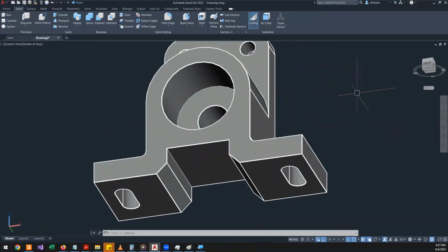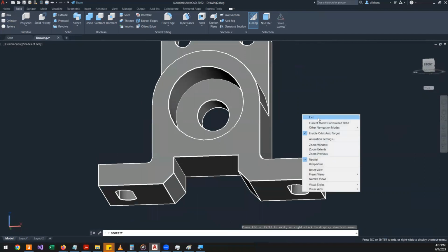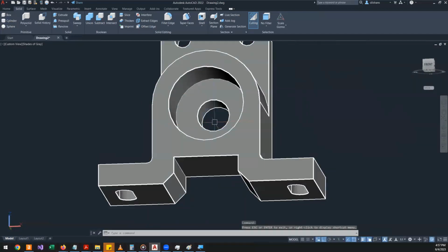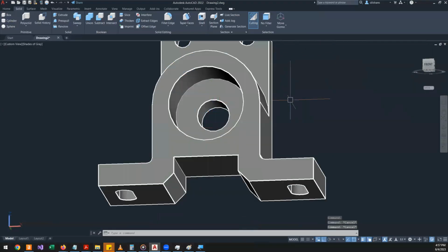If you have a simple modification like that, you can select the face. By the way, if you click on an object, you will select the entire object. So let me change back to move. But if I want to select just a face, or maybe an edge or a vertex, press and hold the control key.